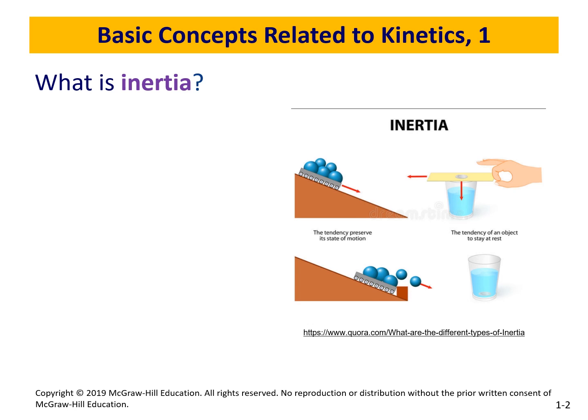Now, this is the general physics definition of it. But do you remember something called the moment of inertia from statics? Let's say I have these pieces of paper, right? If I'm trying to push on them like this, it will bend, right? Would it be easier to push it here or this way? So the direction of doing the compression, do you think it's harder this way or this way? This is harder, right? Because the geometry is giving me more elongation. So this piece of paper is resisting bending based on geometry. And that's the same thing as inertia.